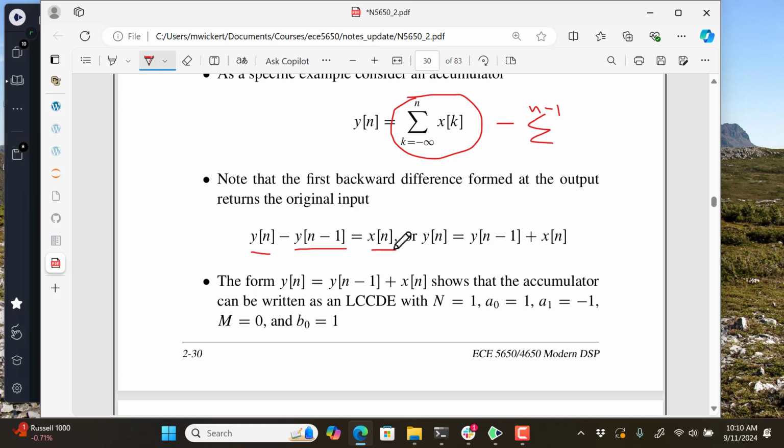So just rearrange that now, and we can see, aha, the accumulator is very efficient, extremely easy to implement. All we're going to do is get the new output from the accumulator by taking its previous output and slapping on the new input. Does that seem cool? It's so wonderful, and it does form a difference equation. This is a very simple first-order difference equation.